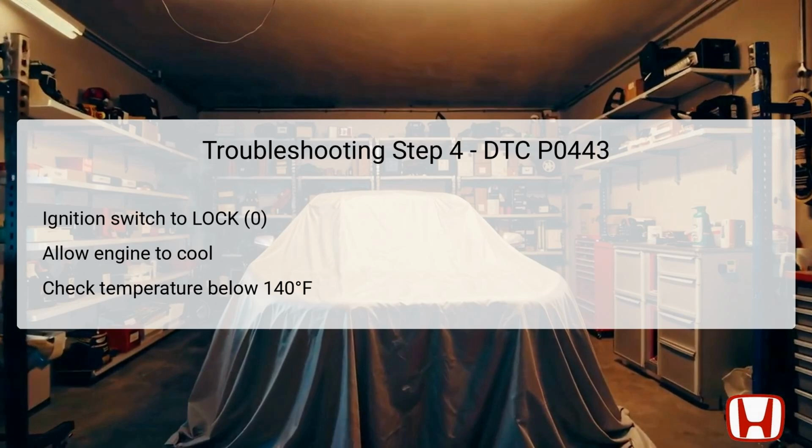It is essential to let the engine cool down to below 140 degrees Fahrenheit, 60 degrees Celsius, before proceeding, because working on hot components can pose safety risks and potentially affect operating parameters. This safety check ensures that no thermal expansion or other heat-related issues interfere with the diagnostic process.